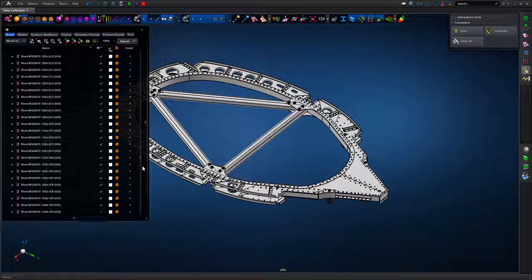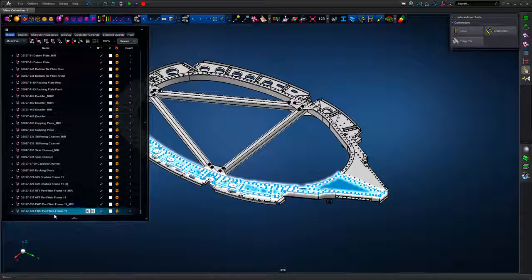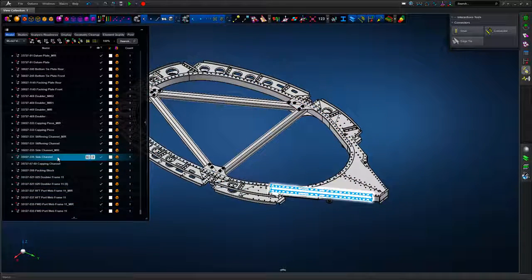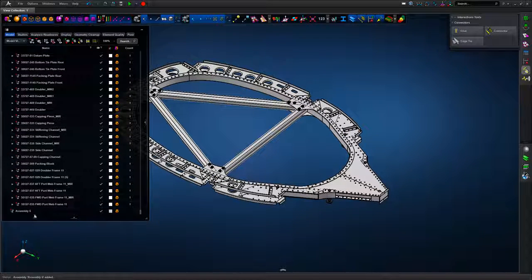So we're going to use the information in the model browser tree. We're fortunate in the sense that the CAD definition has been generated very nicely with discrete names per entity or sub-assembly. So we're going to use the browser search function to pick out those entities and remove them from the structural assembly, as it were. So first of all, we're going to create a new assembly.